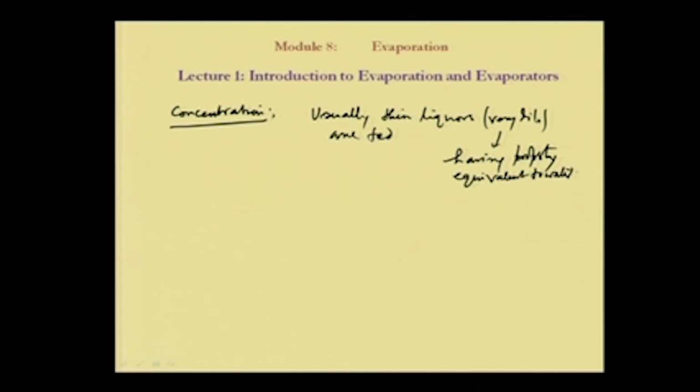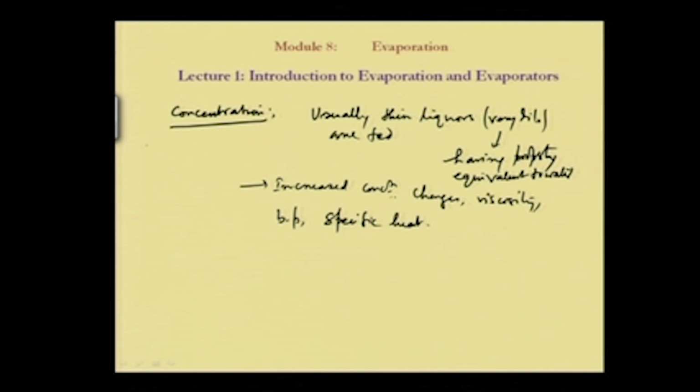But with increased concentration, the viscosity changes, the boiling point changes, which is called elevation of boiling point, and there are many other issues like specific heat, etc. So we have to be pretty careful while calculating how the properties change and how to take care of these things. This is the effect of concentration on the evaporator design.